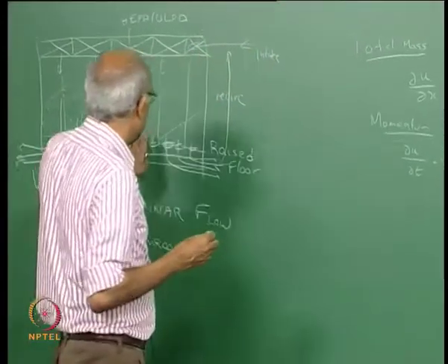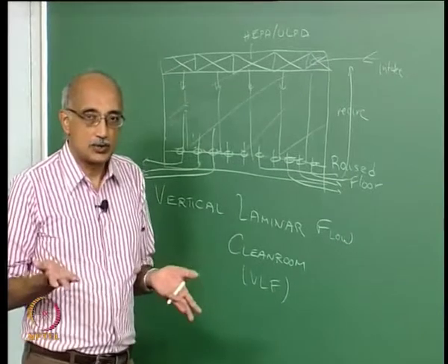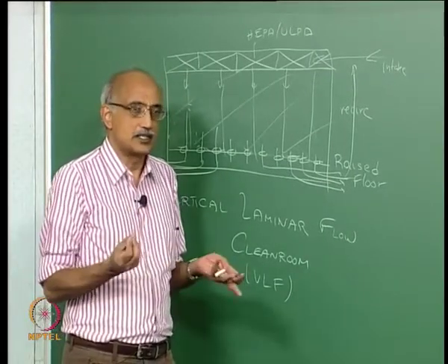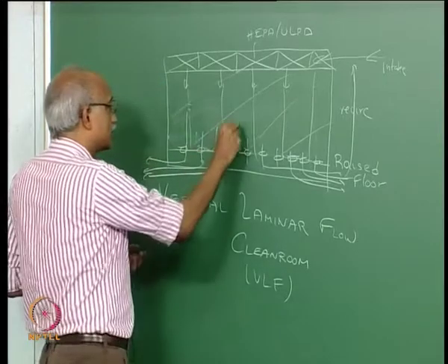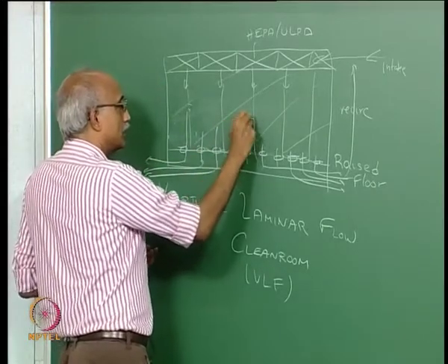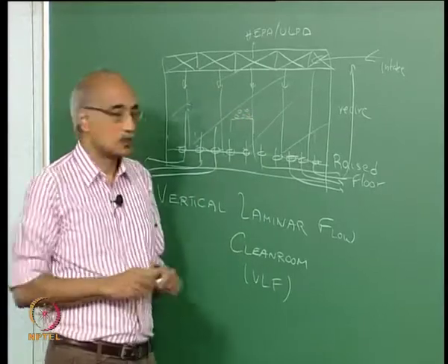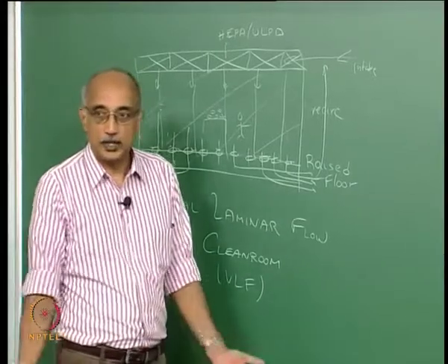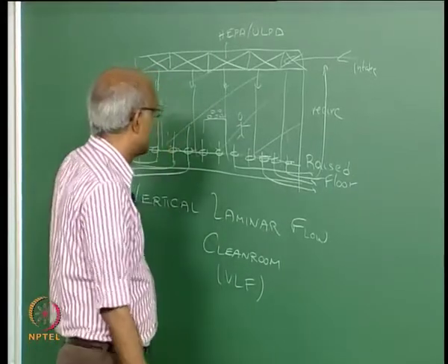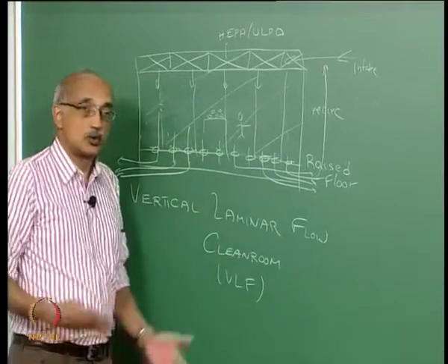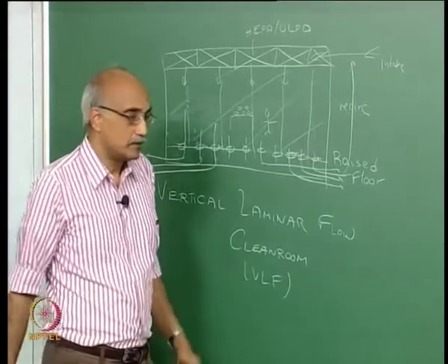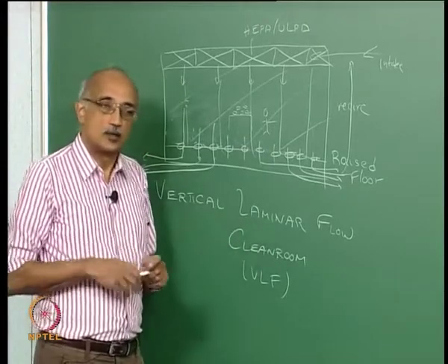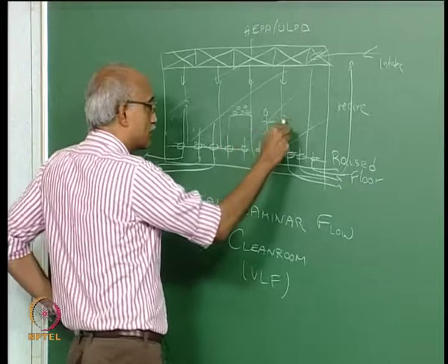Because the assumption here is an empty room, but that's not true. Any clean room in which a manufacturing process is running is going to have all kinds of things in it, right? It's going to have workstations on which you're going to have some parts sitting there. It's going to have people, who may be standing, walking, moving around. It may have various part storage locations. People may be wearing garments, gloves, but most importantly, this person is going to be doing something.